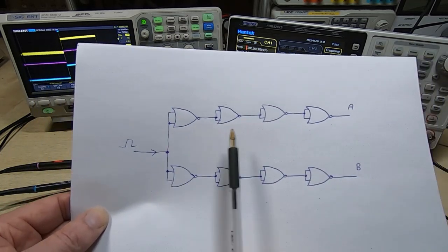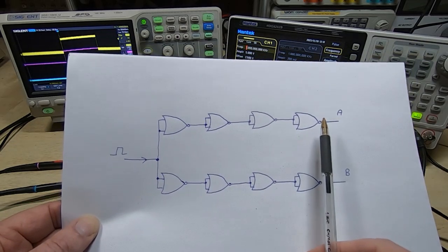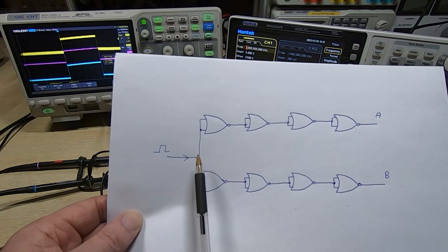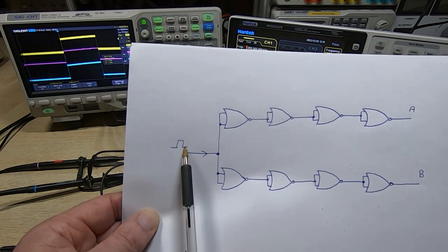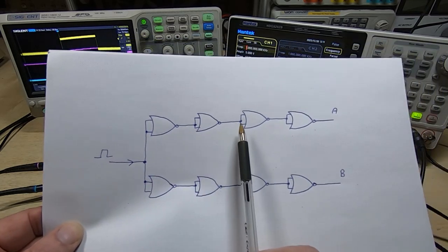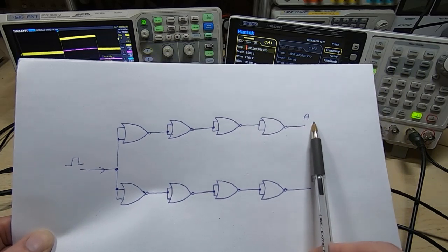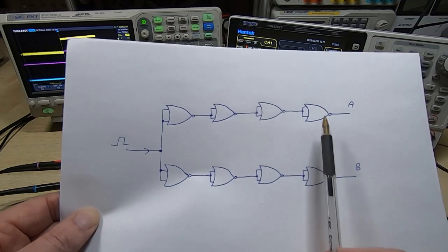So this tends to be a minimum number of gates you will get in the memory decoder and memory select circuit. So the idea here is that you look at the input signal edges as the clock edges for your processor, and then going through your decoder, the resultant edge here shows you the delay between the two, and that's what we're representing here.